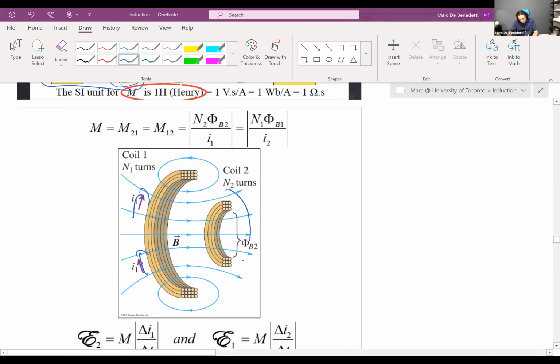And what they do is they take the secondary coil and they actually place it inside. So they usually wrap it smaller, and then that way they can nest it like Russian nesting dolls inside of the primary coil. And that makes it lighter. You don't necessarily have to use the iron core, and it maximizes the M value because they're lined up, they're as close as they possibly can, and all the variables are as optimized as humanly possible.